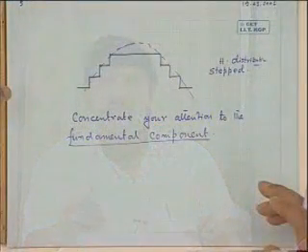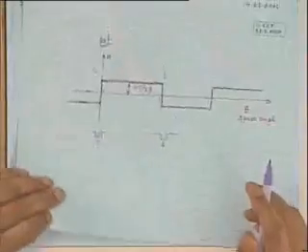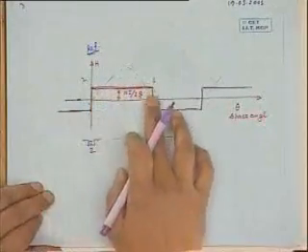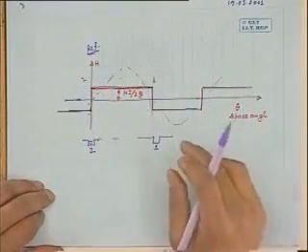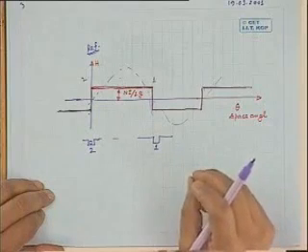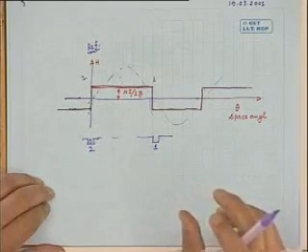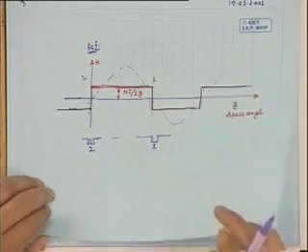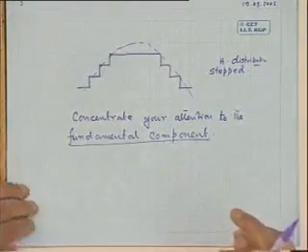Other way, you can tell that is B distribution, let it be sinusoidal. But I wanted to tell how B distribution can be made closer to sinusoid. So in a single winding, if you excite by direct current, the MMF distribution will be this one. It will also have a fundamental component. So what I am trying to tell, be it a single coil or multiple coils connected in series, we will first examine what happens to the fundamental component of that. We will deal with the fundamental component.